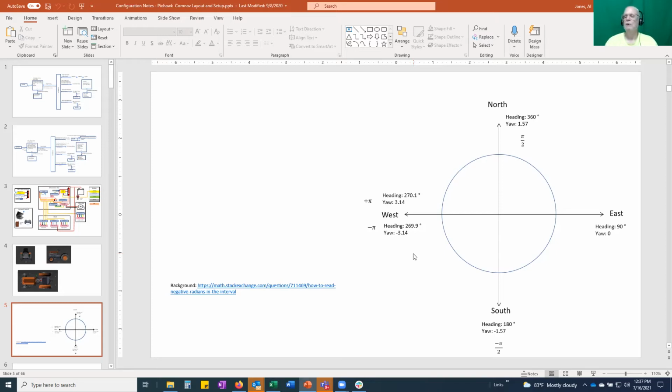I'm still confused when I drive around and think, what should this look like on the screen? Right now, if I pull up my wheel odometry and plot the XY plot from that, and then pull up the output of GPS ODOM, the GPS ODOM, I believe, looks just like the GPS stuff I put into it. So I don't think it's doing the conversion, but my odometry is mirrored in the X direction. When I say X direction, I mean plotting that with PlotJuggler, like a mathematical plot. Yeah, it's mirrored in the X direction.